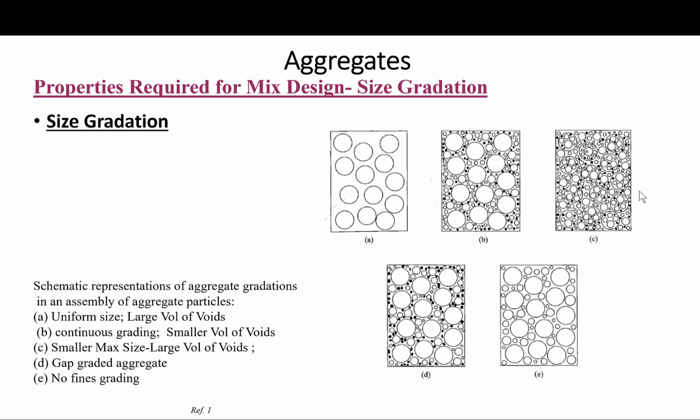So well-graded aggregates will provide that minimum void spacing that needs to be coated by the cement paste, reducing the paste requirements.